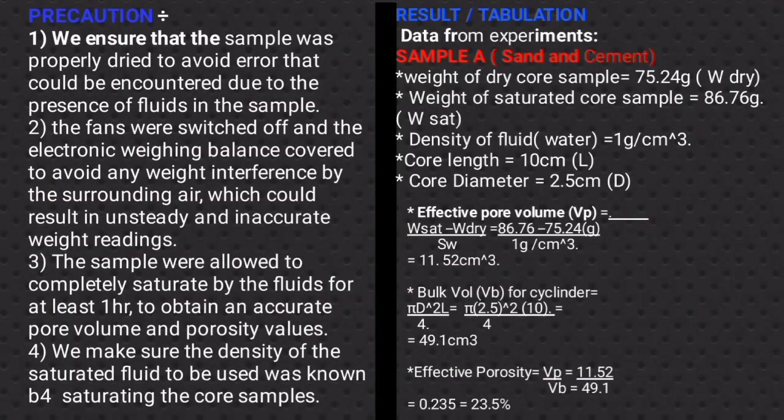Number 1. We ensure that the samples were properly dried before use. Number 2. We ensure that the fans are switched off to avoid interference from the surroundings. Number 3. The samples are allowed to completely saturate, that is, left in water for a minimum of 1 hour to have accurate pore volume and porosity values.